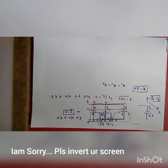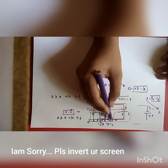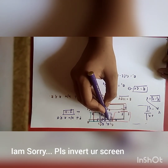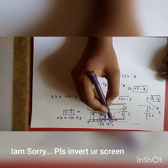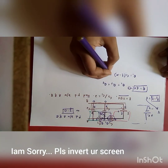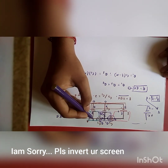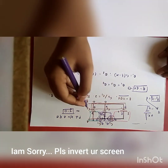Now using this formula, the capacitance of this capacitor is C1. So Q1 will be C1 into E minus X. The potential here is X, the potential here is E, so E minus X will be the potential difference across this capacitor. So Q1, the current passing through the capacitor, will be C1 into E minus X. Similarly, Q2 will be C1 into X minus Y, because the potential here is Y, here it's X. And here Q3 equals C2. This is C2, mind you.